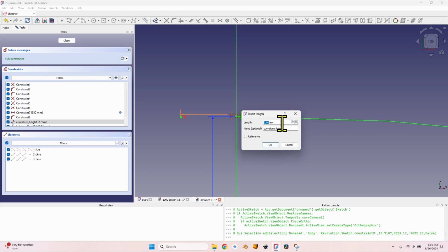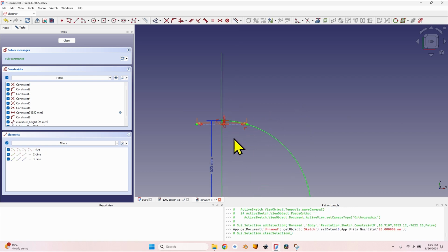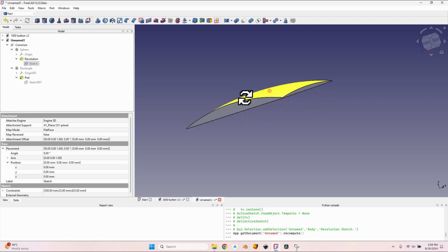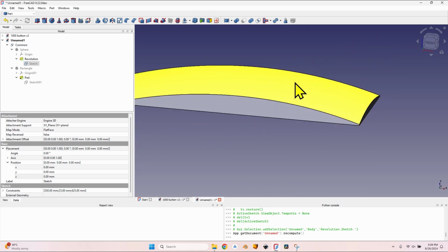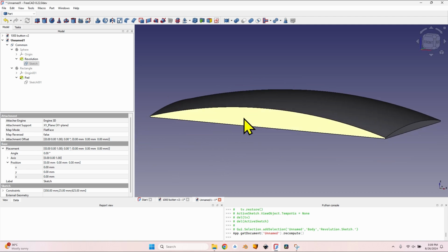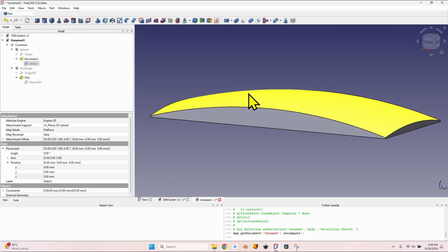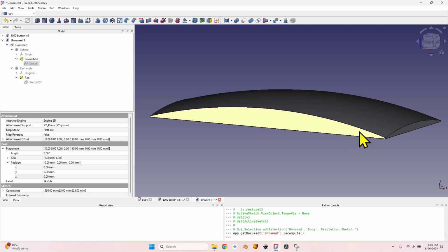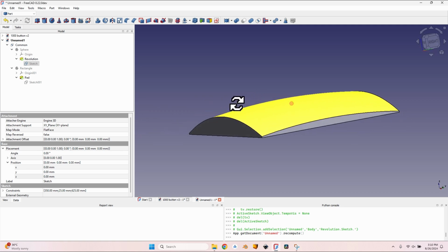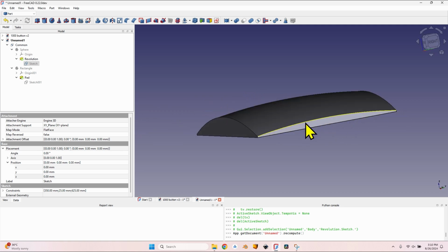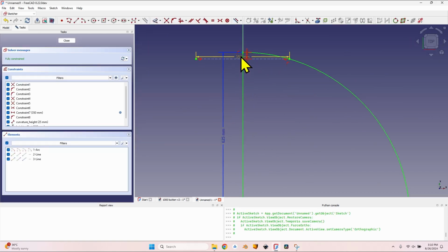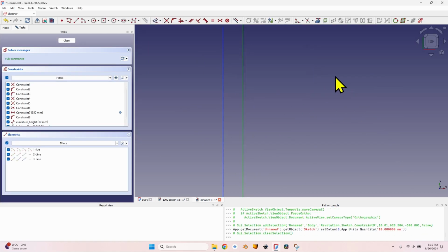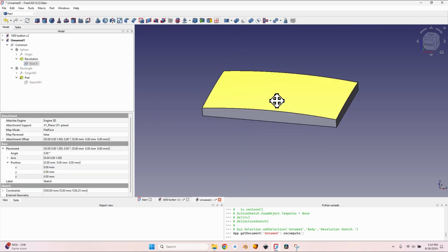Let's write a length of 25 millimeters. Everything went much smaller this time. Click on the close. You can see that I already have some problems. The curvature goes almost all the way down, and that is a normal thing because if I have a rectangle with a 35 millimeters total height and I'm going to cut this curvature from its top, even though at first I expected to have 10 millimeters here in the corner, then I realized that the 10 millimeters are in the center of this side. So since this is curved too, it will result in a much lower distance here. So let's get back to the 10 millimeters that we initially set here. Click on the close, and now we have a pretty decent looking rectangle.